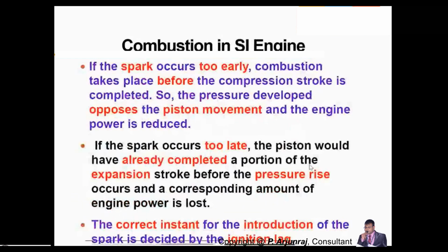Look at this very carefully. We have seen the valve timing diagram. The piston moves from TDC to BDC, and the air-fuel mixture comes in during the induction stroke. When the piston moves from BDC to TDC, which is the second stroke, also called the compression stroke, and it is nearing the completion of the compression stroke, a spark gets ignited, and you're going to get combustion.